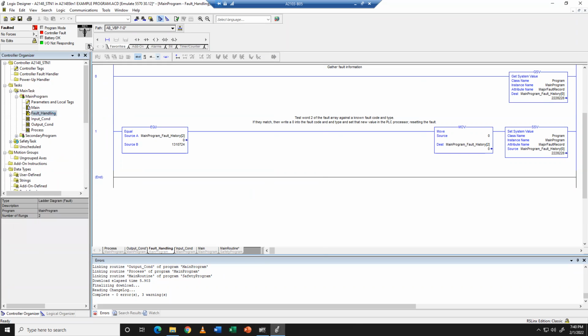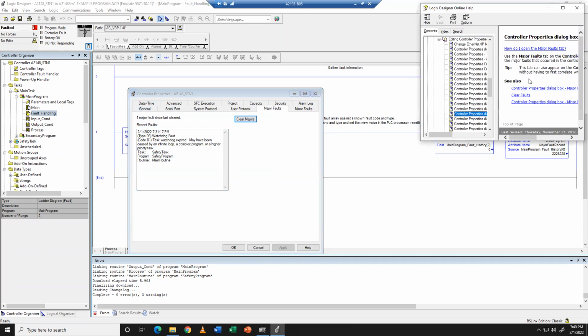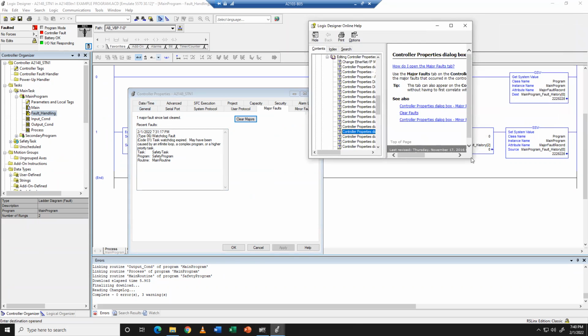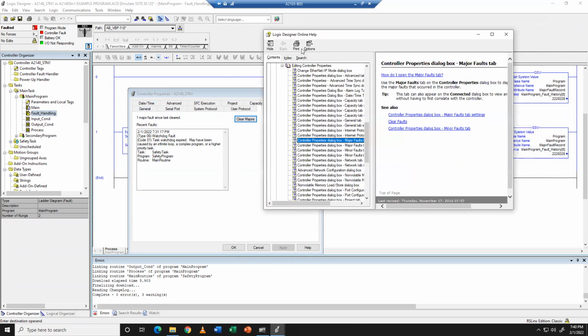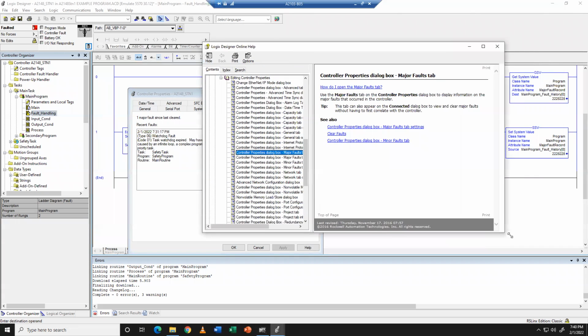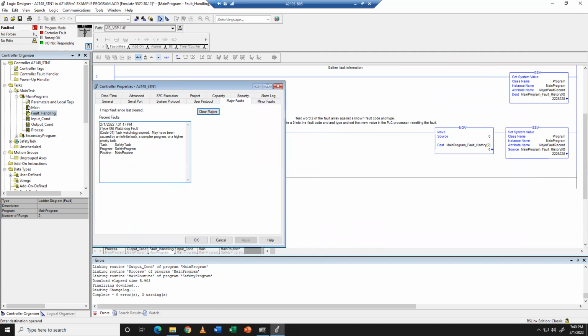If we look up here, again, we can see code type information. And if we were to look in the fancy F1, if you need to find troubleshooting information inside of Rockwell, as long as the person who installed the software installed all of the troubleshooting libraries, F1 will open up the help menu, and it's getting better as well.